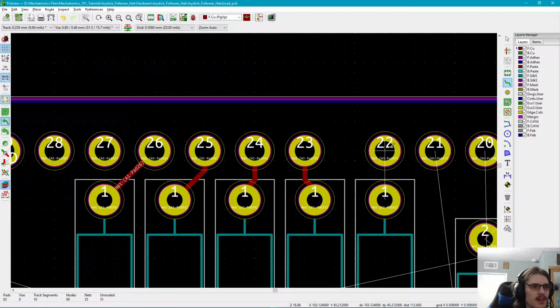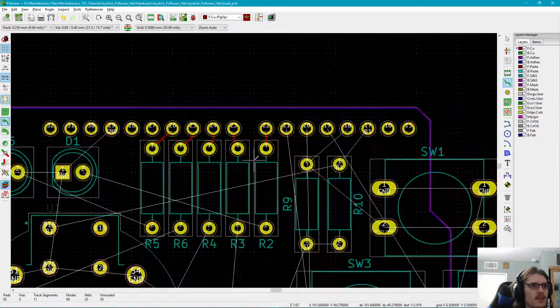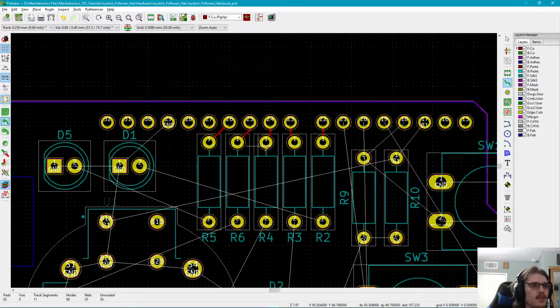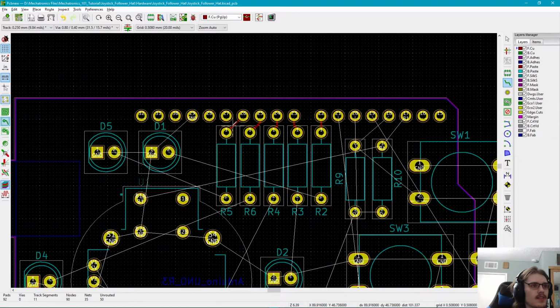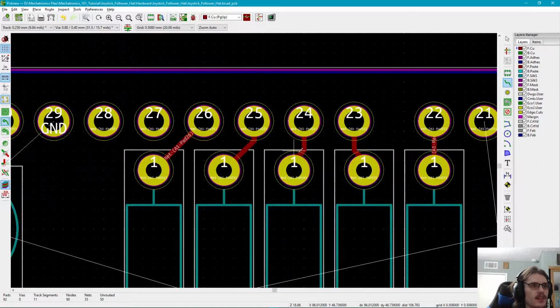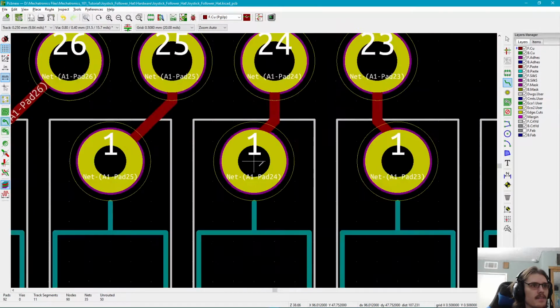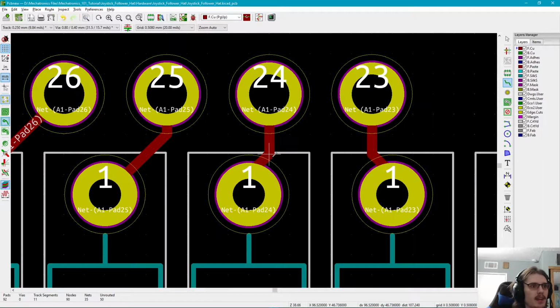The reason for that is because when the manufacturer makes the PCB specifically, the traces, when the process they use it, acute angles, they can sometimes build up acid that will erode the trace itself, and you might see kind of like a rash, or a burn at an area where the board would be made, or where the trace would be, and it can damage your board.